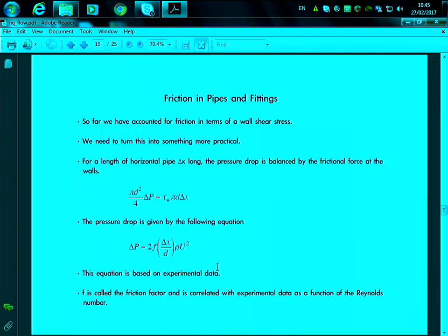You look at the slope of the laminar region. In this case, the laminar flow is 16 over Reynolds, and 16 over Reynolds is normally for the Fanning friction factor. If you have 64 over Reynolds, then it's the Darcy friction factor. So if you find a chart and it's not specified whether it is a Fanning or Darcy friction factor, look at the slope of the laminar flow and how it is defined.